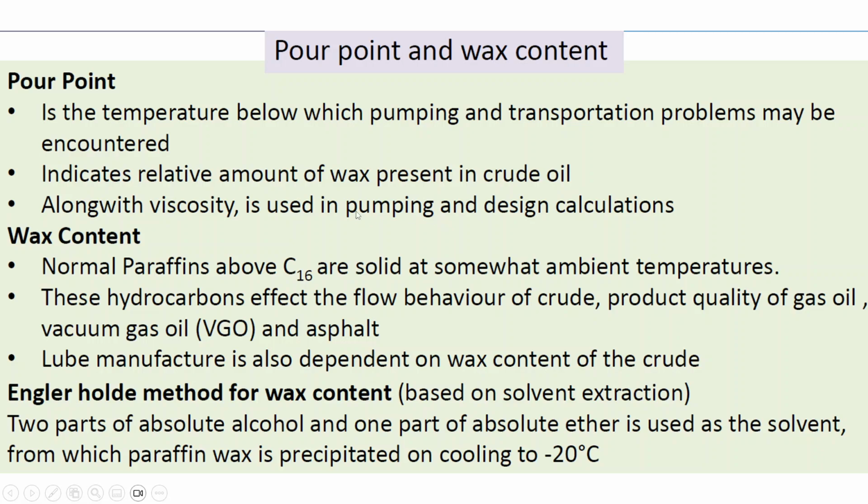Along with viscosity, it is used while determining the pumping and designing calculations. Pour point plays a very crucial role. Wax content is basically the normal paraffins above C16, which are solids at somewhat ambient temperature. These hydrocarbons affect the flow behavior of crude product, quality of gas oil, vacuum gas oil, and asphalt.